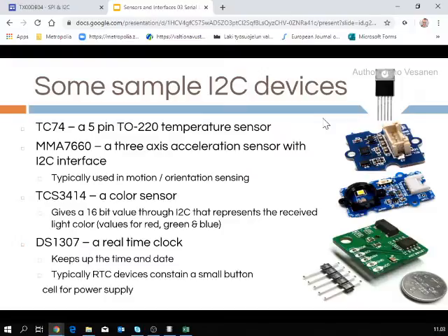And actually, the I2C bus is also used sometimes between processors. That's a simple way. In addition, at least 15 years ago, there were plenty of computers which had the boot code on an EEPROM on the I2C bus, because you only needed to boot the computer 2 times a day at that time.